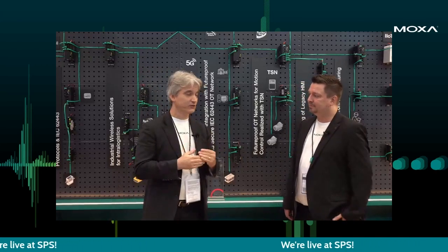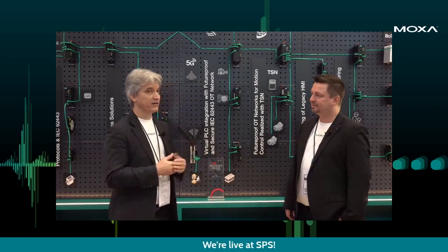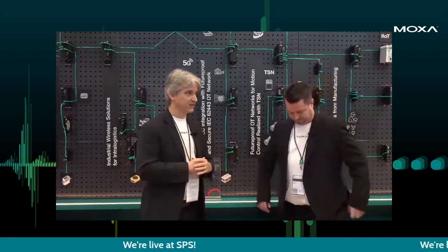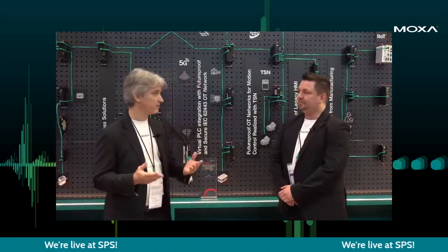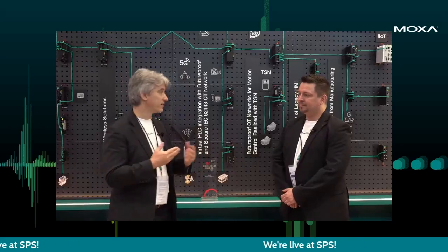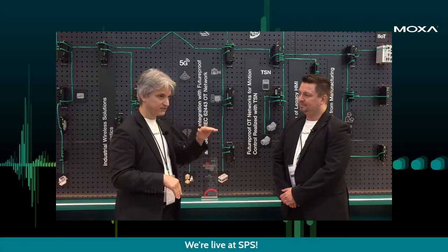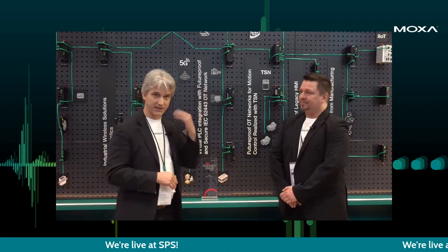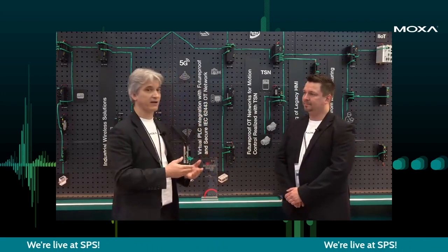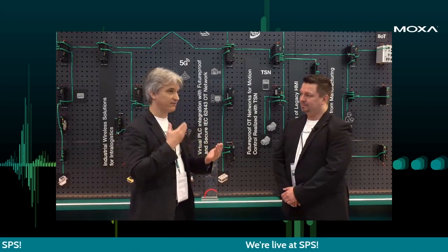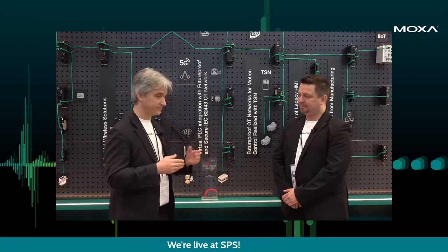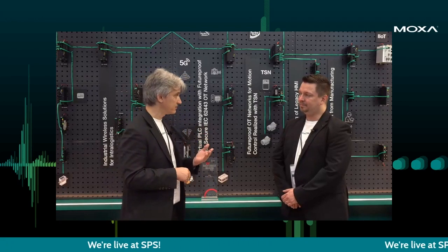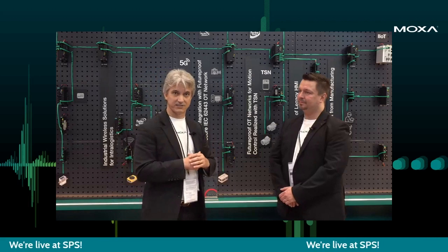But when you do, you need to take some precautions because maybe the OS is outdated and shows some vulnerabilities. Maybe the hypervisor, a software layer between the PLC and the hardware to make it independent from the hardware, so it doesn't matter anymore if you have a Xilinx, an ARM, whatever, is misconfigured, which brings extra security concerns.